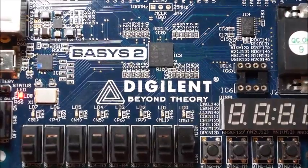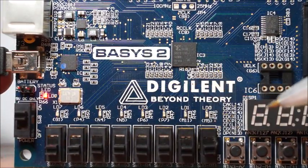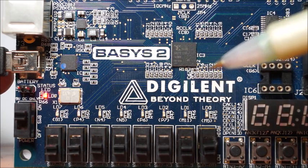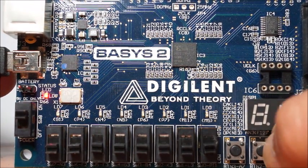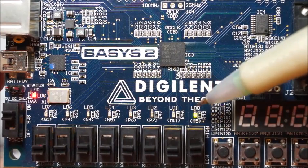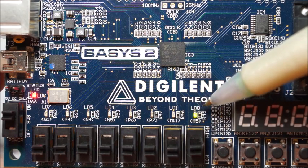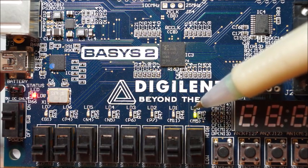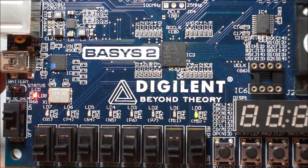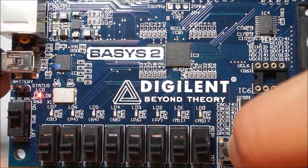And as you can see, none of the LEDs are on right now because the register that I write to starts off with a 0 value. So now let's go ahead and press, and as you can see, this LED just lit up. So that means that the register file has been written a value of 1 through this button. Now if I push the reset button, the LED should turn off.